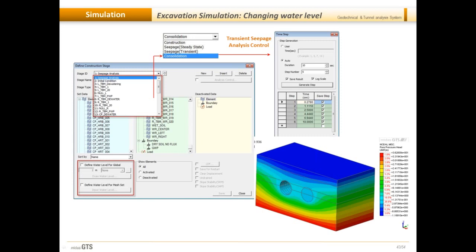So these are the long-term effects that happen, and this is happening due to the consolidation movement and the dissipation of pore water pressure from the clay layer, and this deformation will continue to occur until the pore water pressure equilibrates and appreciates the presence of the tunnel interface there. So till the time it stabilizes, you will continue to get deformations and thus additional forces on the tunnel.